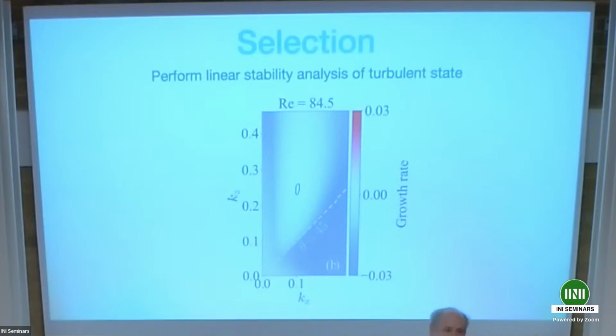Almost any kind of turbulence closure you introduce is extracting energy from the mean flow and putting it into turbulence, that production term. Well, you see it as a divergence of the Reynolds stress in the momentum equation. That's all you need. And so that angle is extremely robust. And I ought to be able to tell you, and I would like to, within a few months, possibly, what sets that angle.